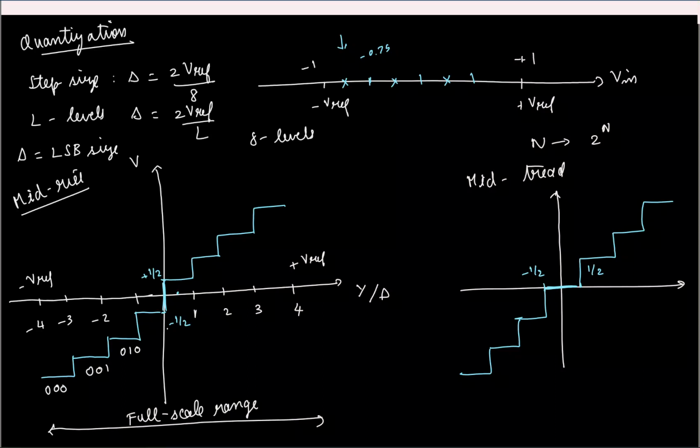Okay. And unlike sampling, which we looked at before, is sampling a linear or a non-linear operation? When is an operation linear? What is the condition for linearity? For 0 input, I should have 0 output, homogeneity. And if I scale the input, the output should also scale. If I have a 0 input, when I sample it, will the output be 0? Yes. If I have some input and scale that input, after sampling, will the sampled output also scale? So it's linear or non-linear? It's linear.